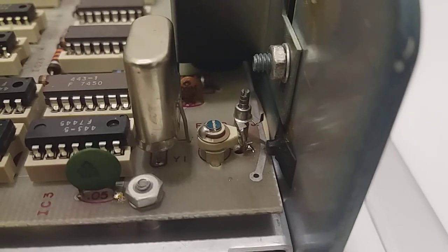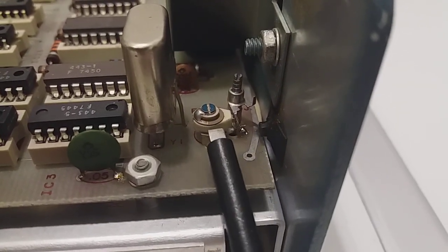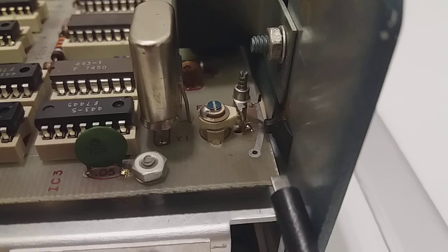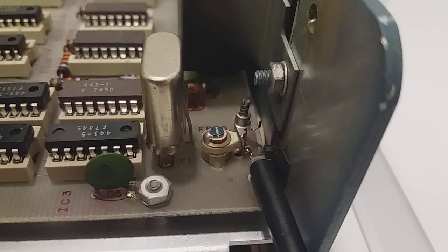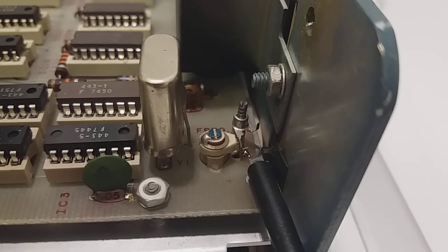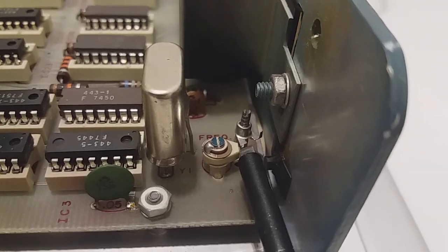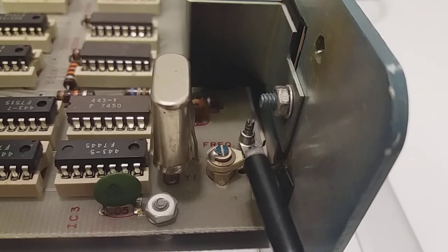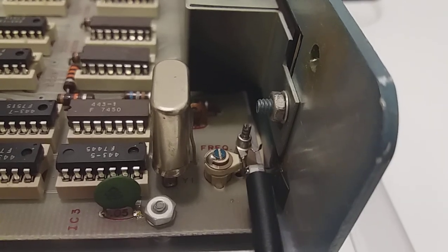just connect this little trimmer in series with the main trimmer. So here you see the main trimmer, and I have just cut this leg here with a fine cutter, not completely. One of them is going to the PCB, that point that I have soldered, and it's bent a little bit to the right, and the other stays in the air here. And between this pin of the main capacitor and the other pin that goes to the PCB, I have soldered this fine trimmer, and this should in theory yield even less capacitance, at 0.3 picofarads.